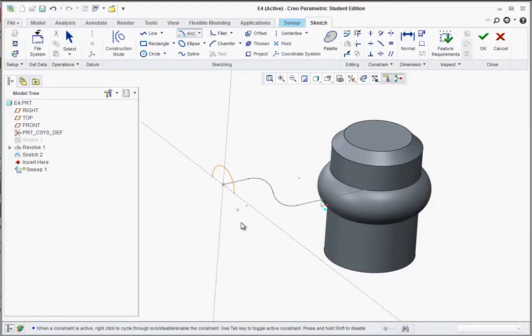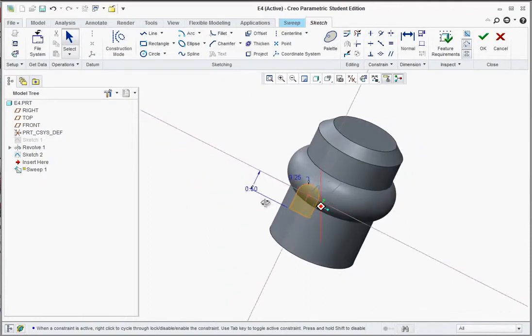Click, and now select the Line tool, and off of the vertex of one of those, drag a horizontal line straight down. You should get the little H. Drag it to the right, and when you get the little equal or little lines that show that it's aligning, click and connect it. Middle click a couple times. Let's change this to 0.5 and 0.25.